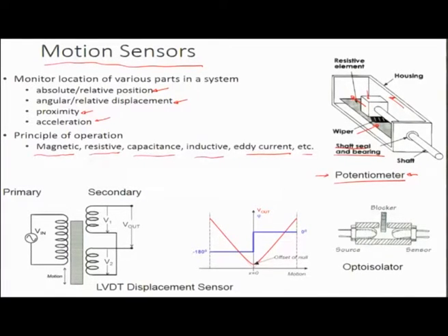So if supposing a linear motion provider which needs to be sensed is coupled to this system, which helps to propel the shaft in the forward direction along with the block, it will show up if I connect this to a voltage divider circuit and assume that motion gets executed, meaning a resistive change is there. So in a very simple manner, you could look at the resistance per unit length and compute the velocity of motion of an object connected to this shaft right here, by looking at the delta R as a function of time. So this is one of the very simple motion sensors.